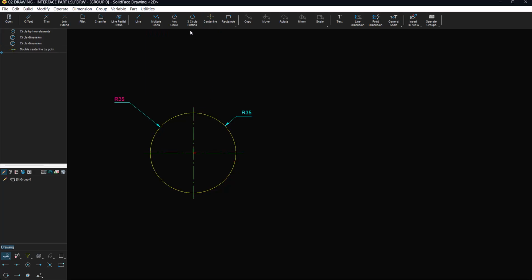Let's create a new circle. Activate the relative point option. When the mouse is closer to the circle, the center is highlighted, and the cursor icon is changed, indicating a point relative to the circle center. Now move the circle center about the x-axis relative to the center of the reference circle.